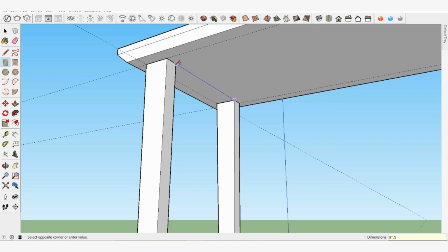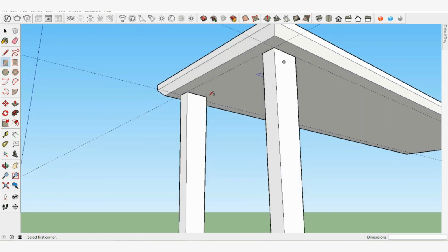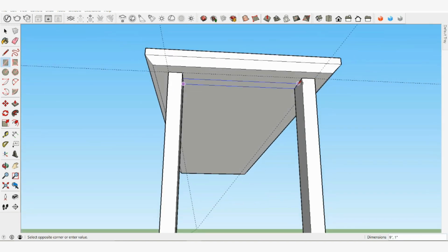As a general rule then, if you don't plan to copy an object, grouping it is fine. But if you think there is a chance it will be copied, make it a component and use groups and components throughout your model to keep objects separate and unique. Now let's return focus to our table.